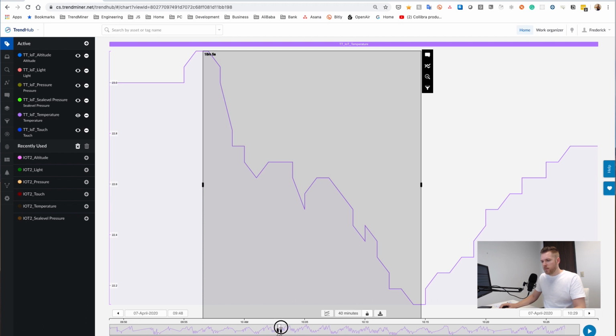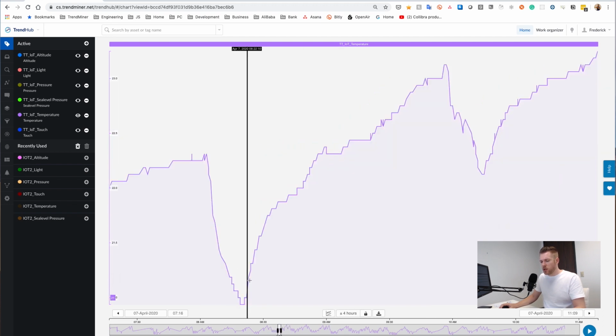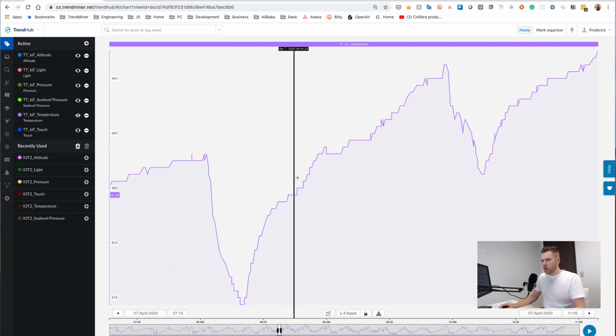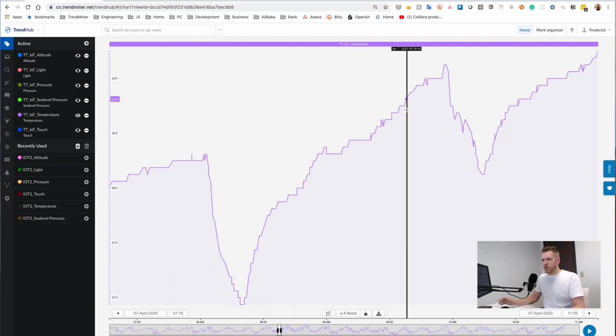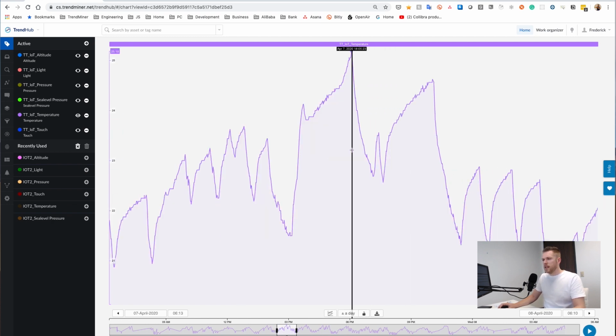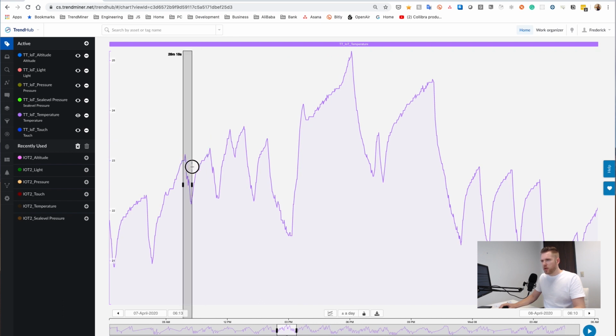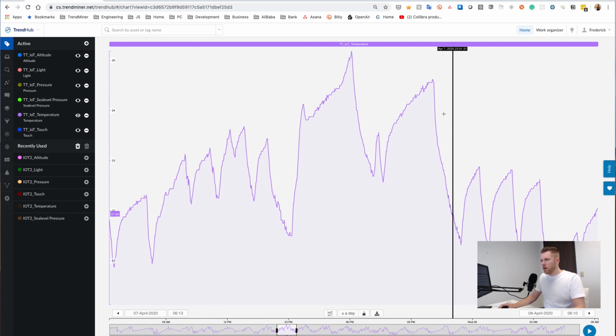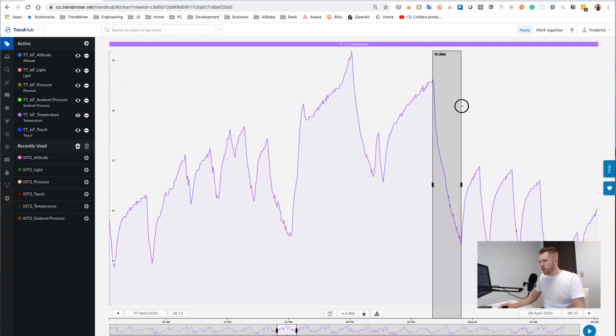Then, of course, the air conditioning will shut off again, after which slowly but surely the temperature will rise up again. This is of course because direct sunlight is hitting our patio, it's hitting our windows, it's heating up the inside of the apartment again. And then whenever the next set point threshold is triggered, we will again trigger the air conditioning to get the temperature down. Now, if you look in this data set, there are a few short bursts, as I mentioned, about 20 minutes, but there's also a couple of larger periods where, in this case, for example, we have about an hour and a half of air conditioning being active.